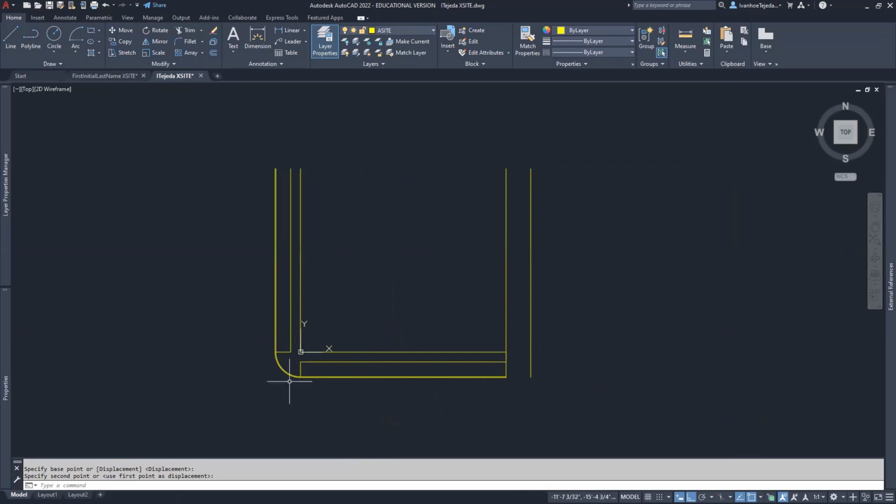And now I'm going to take this information and mirror it to the other side. Not that I need it, but I'm going to include it anyway, just in case. And it's also a good way to practice the commands. So now what I'd like to do is mirror that over. And I know that the mirror point is going to be somewhere in the middle here. And I showed you how to use the midpoint between 2 points before, and I'll do it one more time now. I'm going to type MI and enter.